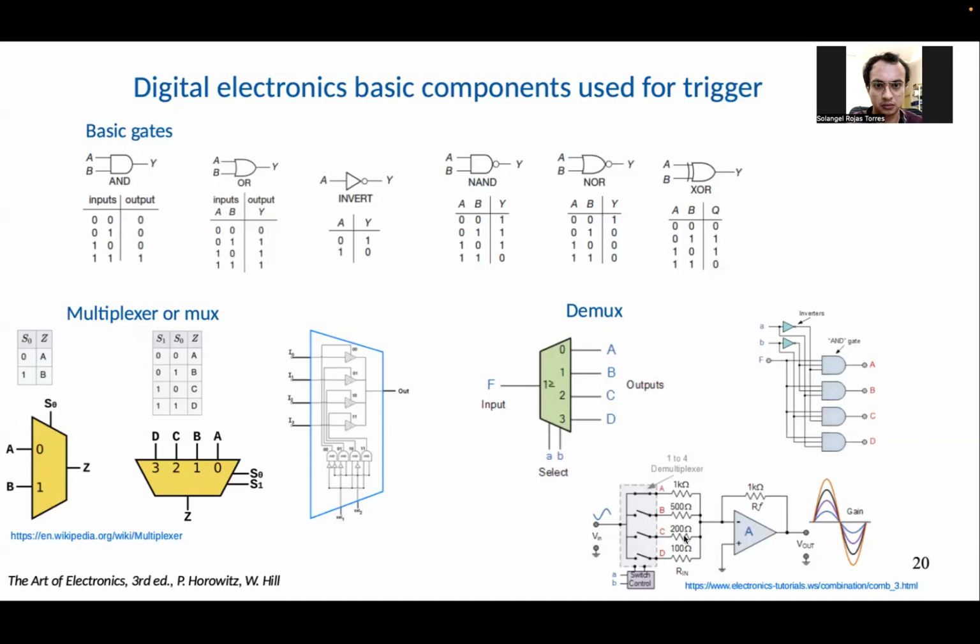And this is an example of a use of the multiplexer. You have, for example, one input and internally in some circuit different gains for an amplifier. So you can select with the multiplexer a different resistor, which means different amplification factors. So instead of having a mechanical dial, you have some electronics, the multiplexer.